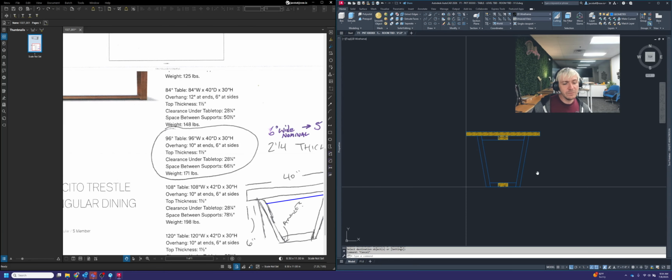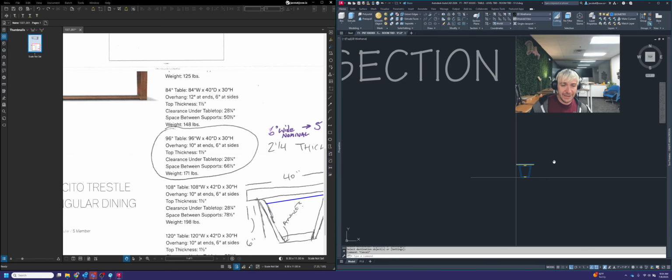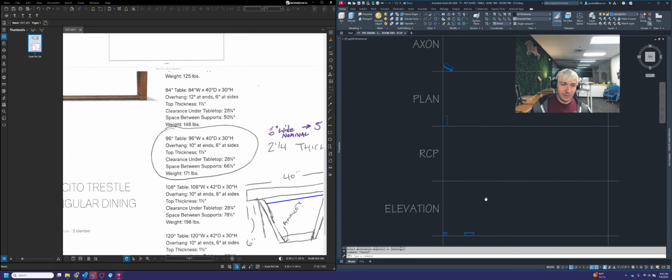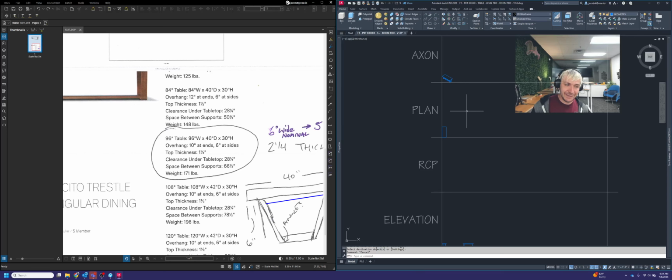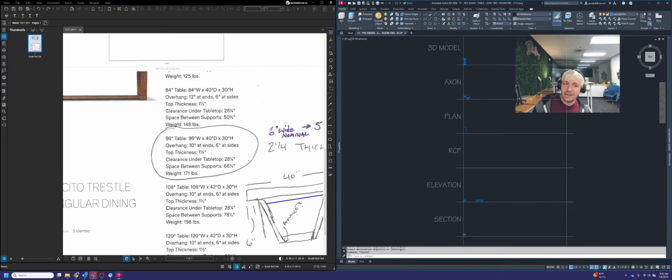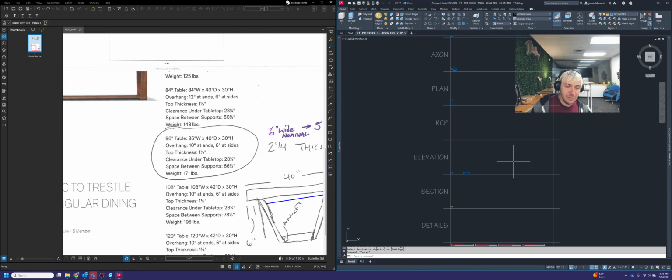So I've got all my solid lumber hatched, and I've got all my views placed, and they're all on by layer, geometry, and the line weight is set to by layer. So now that I've got that, I can start to put this on paper.